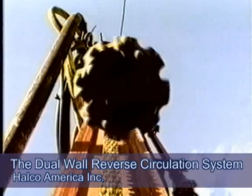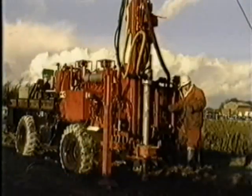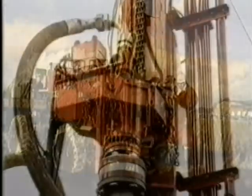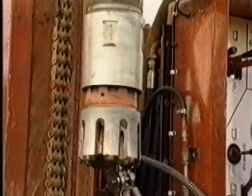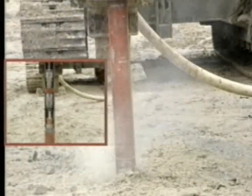The dual-wall reverse circulation rotary drilling system is primarily used in mineral drilling exploration, where accurate chip samples of the geology are required. While not typical to well construction, it may be used in remote locations or where more suitable equipment is not available. This system utilizes rotary crush and rotary percussion cutting actions, offering fast penetration rates and clean representative samples.